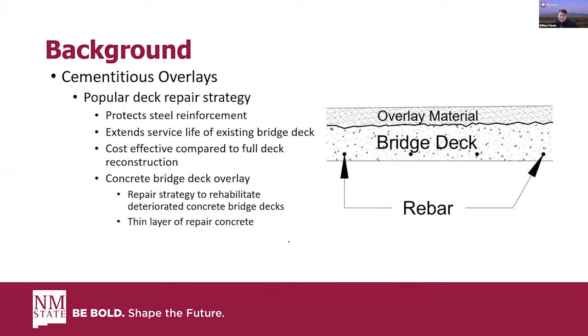Okay, so first off, what is an overlay? It's just a popular deck repair strategy that protects steel reinforcement by providing extra cover as shown here in this illustration. And it can extend service life of existing bridge decks and can be a cost-effective alternative compared to full deck reconstruction. An overlay is a repair strategy to rehabilitate deteriorated concrete bridge decks by providing a thin layer of repair concrete as shown in this illustration.